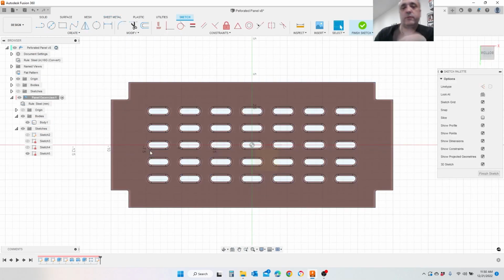The reason why I want to do this on the back surface is because when you're going to do bending, instead of using a profile, it's going to bend it on that line. So whichever side that line is on is the direction that it's going to bend it above or towards. You'll see how it goes when we do it.